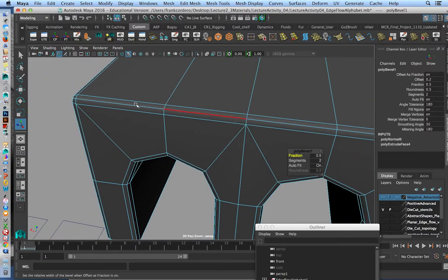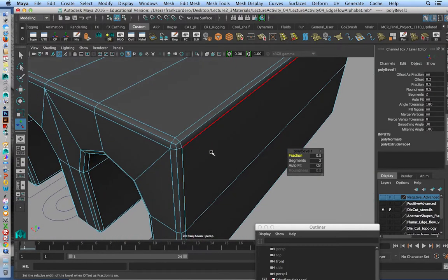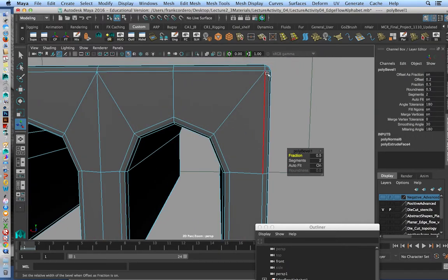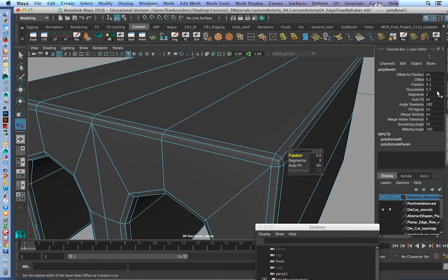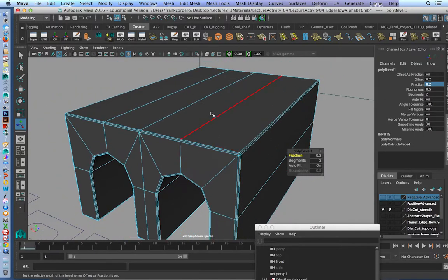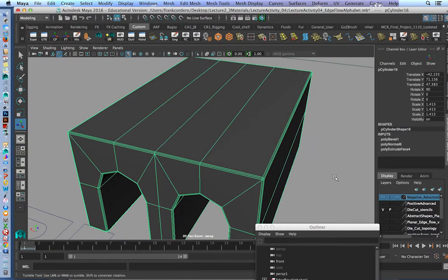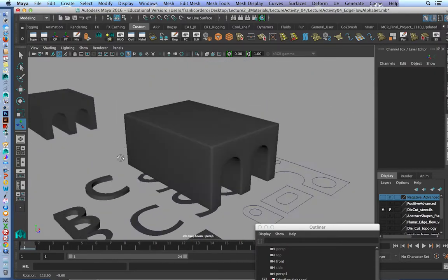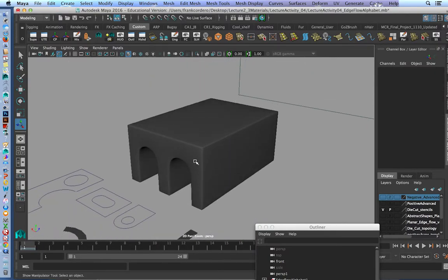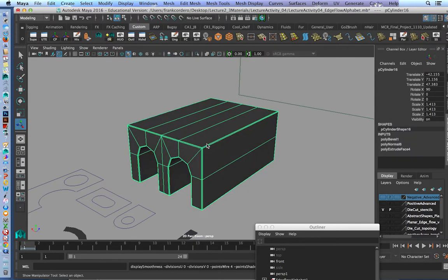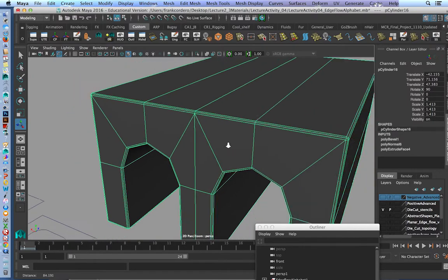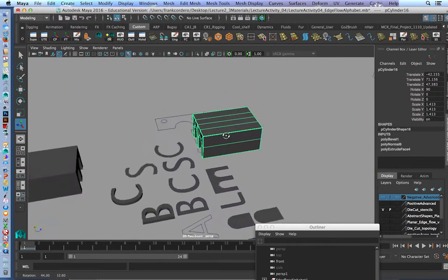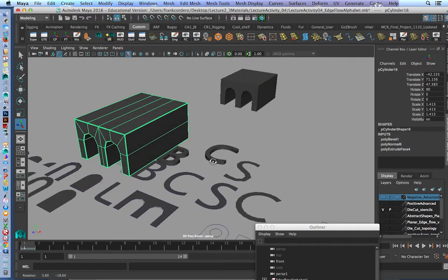In the past, we used to get this weird artifact here in the corner, but now it's fixing those corners where the star junctions, and it's creating that pathway that I was telling you about. And take a look, none of that extra cleanup or wonkiness, and all we have to do now is just dial in, make the thickness of the edges what we need it to, and then hit the 3 key, and that's so much easier to do now in 2016. All right, so that might be the most direct way to do the same thing, just by selecting edges and beveling.